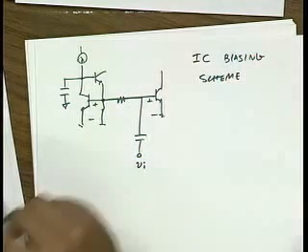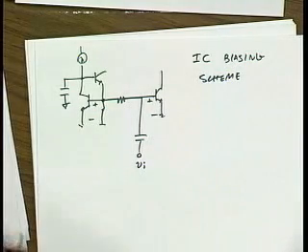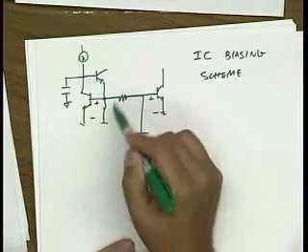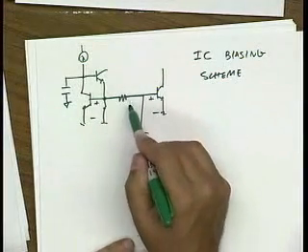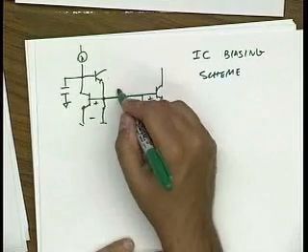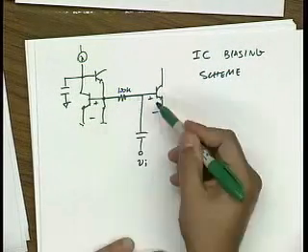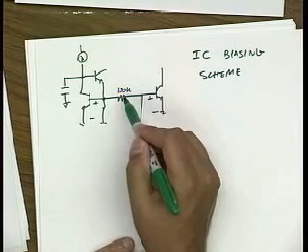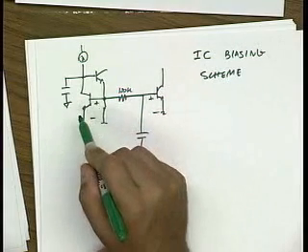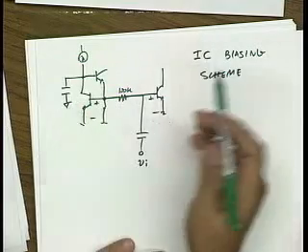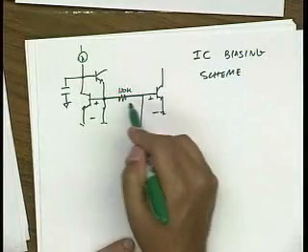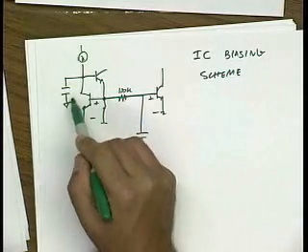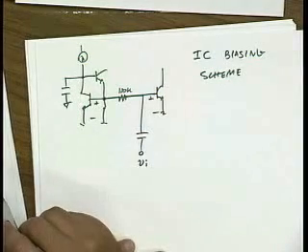Could you just explain the function of that resistance and capacitance once again? Sure. This resistance is there because I don't want my input signal to modulate this. I want this to be constant. So this resistor tends to reject that. It introduces a large resistance, this might be 100K. So the signal that reaches here gets attenuated by the input impedance divided by 100K. Now the input impedance of shunt feedback is very low, right? It's roughly 1 over gm divided by beta. So this could be a few ohms. So the rejection is a few ohms over 100K, almost nothing. This capacitor is here because this is a feedback loop and I need to compensate it.